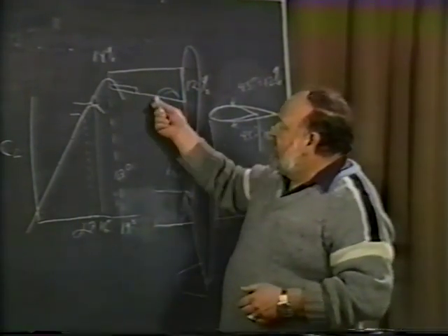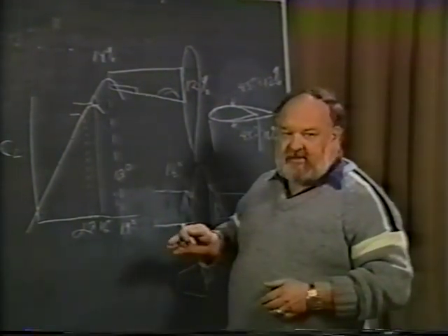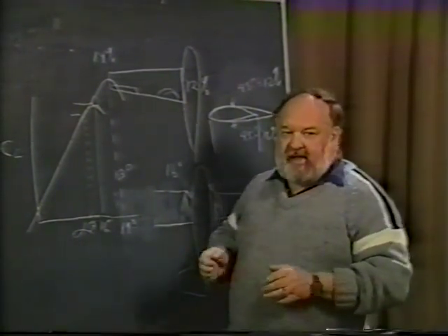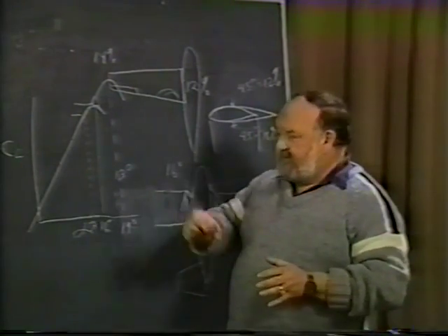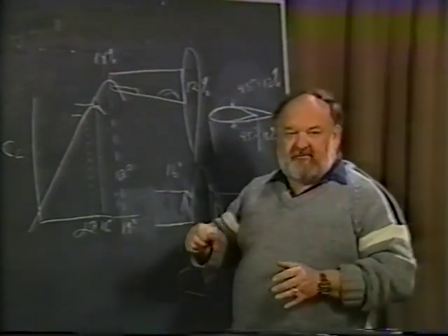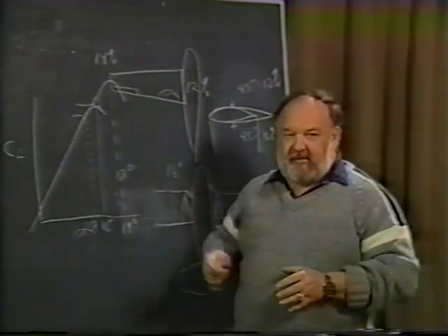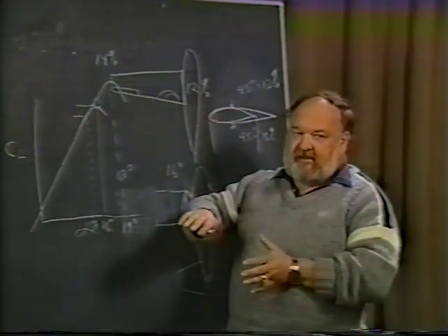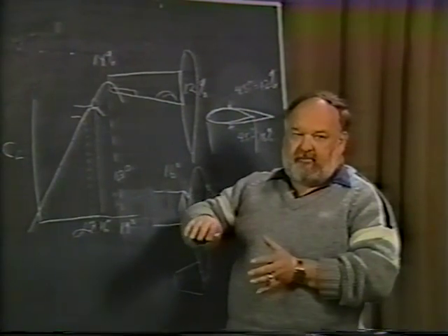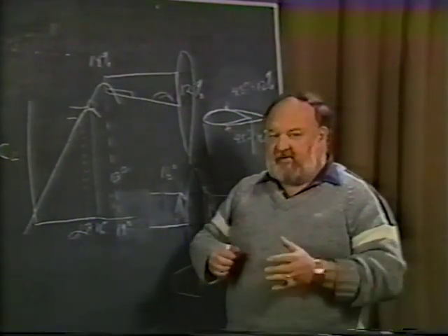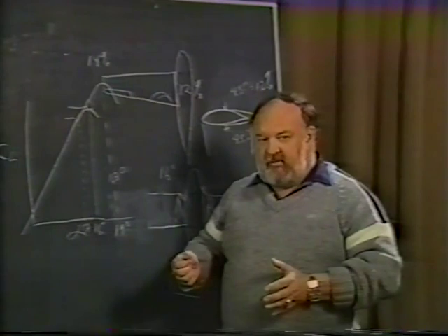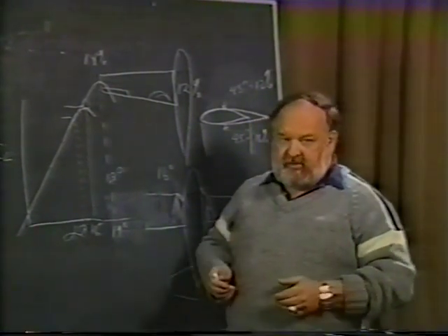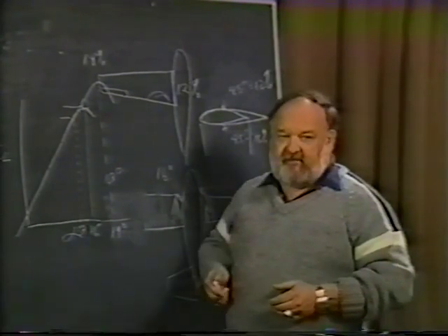In the case of this design, we could actually sit there, be buffeting, getting this inboard section to be separating, and as we're doing that, be able to move the ailerons right and left, no problem. I'll get beautiful roll control out of it. So this meant that as you were turning from base to final, if you accidentally let the airplane get too close to stall and start getting a little buffeting and realized you had a problem and forgot good judgment and went ahead and moved the ailerons as opposed to getting out of the near stall condition, you didn't do a major mistake. The airplane itself could recover it.